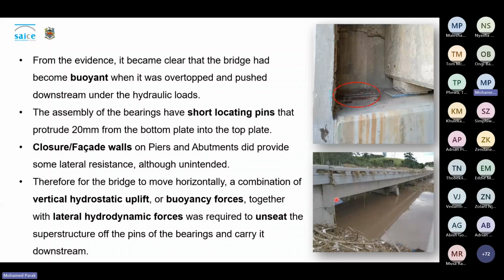Therefore, for the bridge to move horizontally, a combination of hydrostatic vertical uplift or buoyancy forces together with lateral hydrodynamic forces was required to unseat the superstructure from these pins and carry it in a downstream direction. And this theory was tested with some calculations, which I'll show in a few slides later.